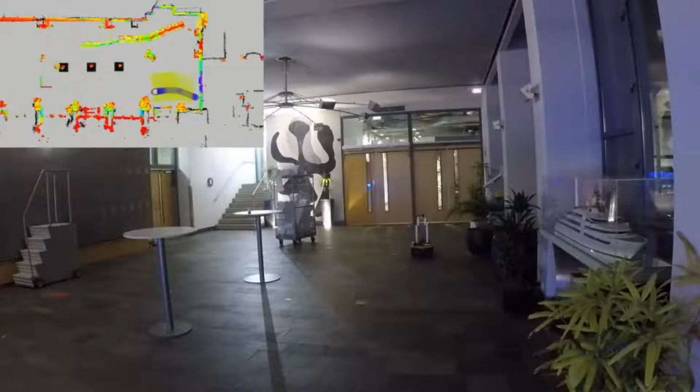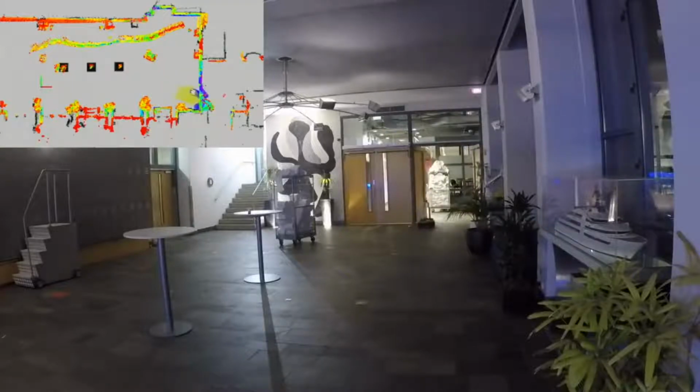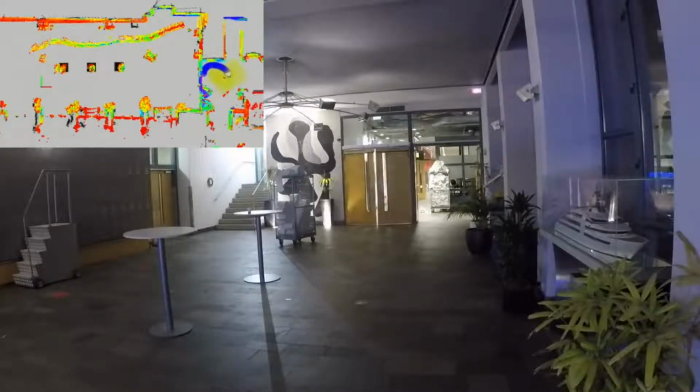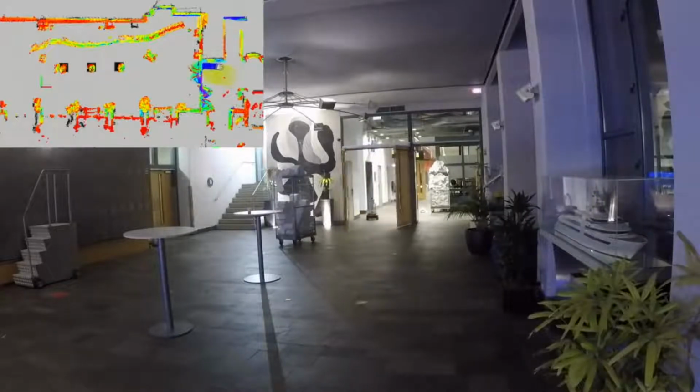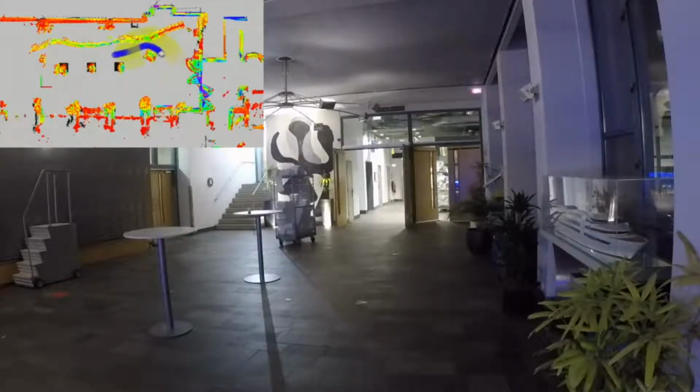Our method is fully implemented on board of a mobile robot, including localization and perception based on sensor data, and runs in real time thanks to its lightweight implementation. In this experiment, we show how we avoid collision with the static environment in an updated occupancy grid map. The yellow area in the visualization represents the polygon convex region, being the feasible set of solutions for the optimal control problem. The feasible region is affected by the doors that have to be opened and the obstacle on the